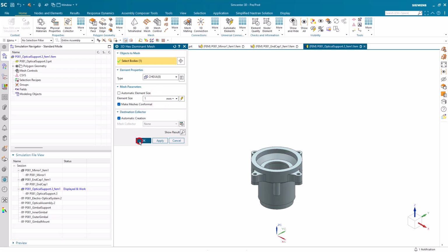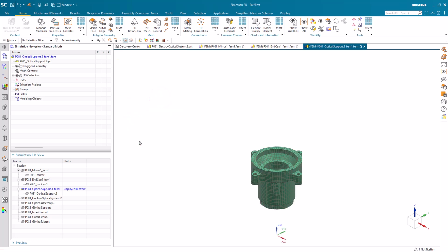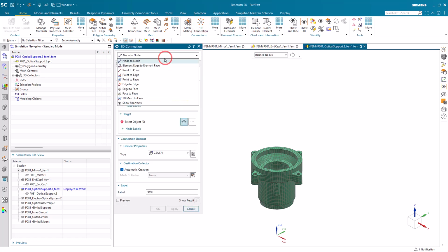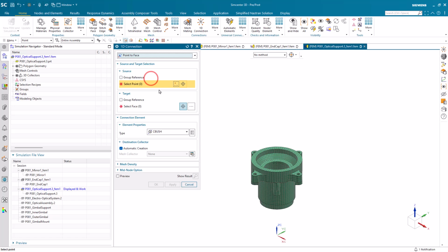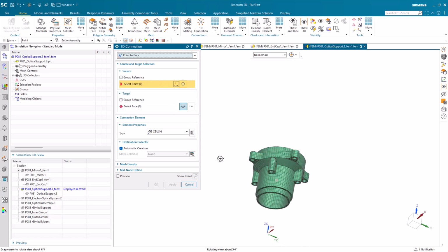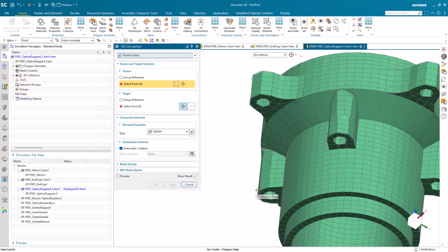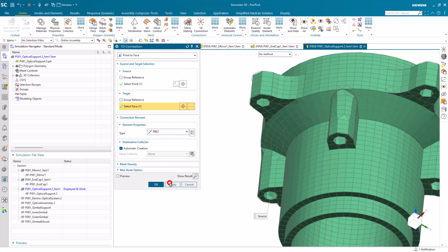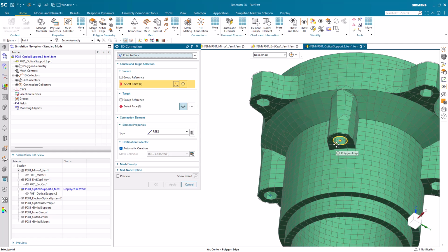For all of these, by default, the mesh collector and physical properties are inheriting the material from the CAD model, which we've already assigned materials to. Now, because this component is going to interface with our superelement, we need some 1D element spiders to help facilitate that.